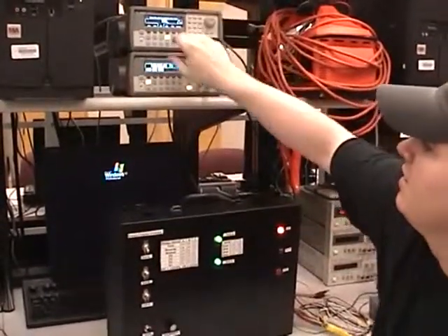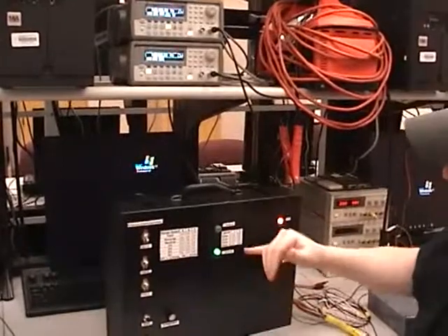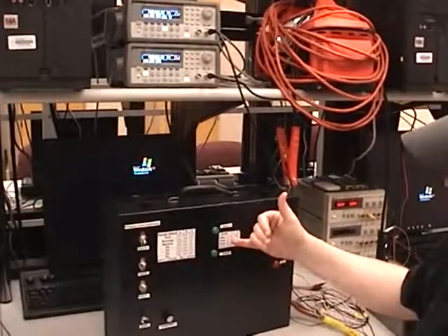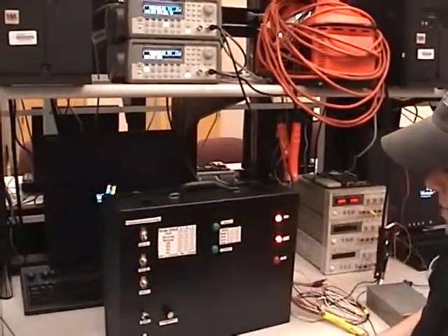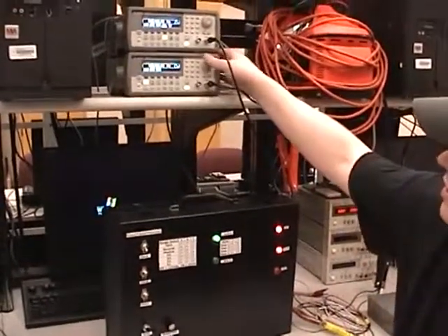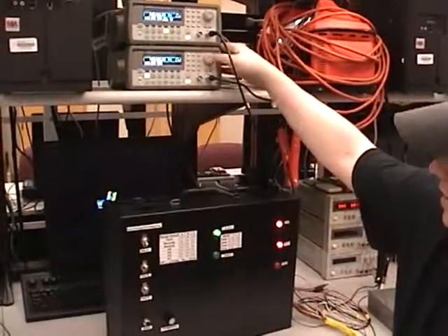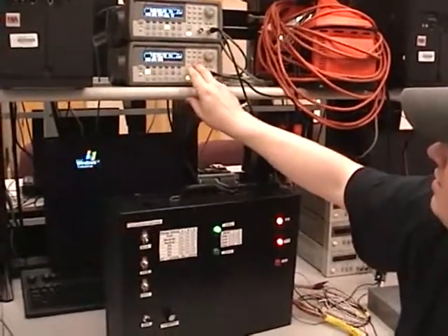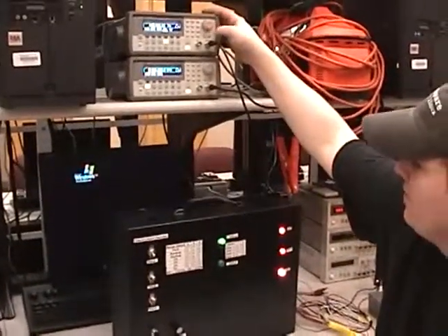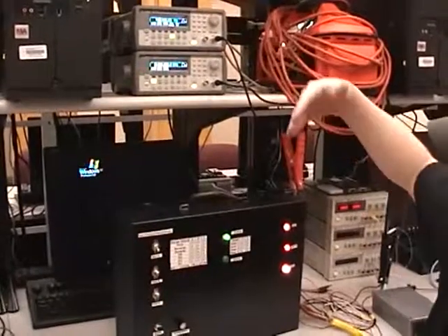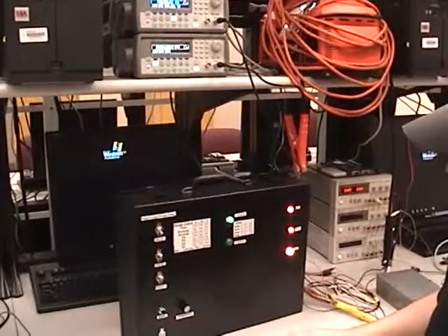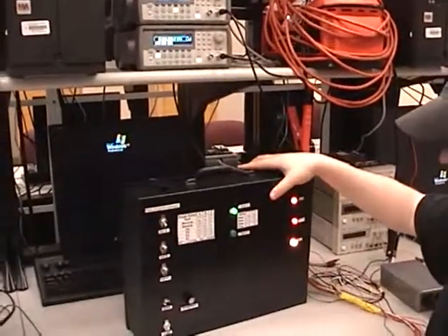So we'll show you again that it shifts, and then your RPMs in your car are dropping because your gear ratio has changed, and then it does the analyzing again, and then you see it wait, and then you get the fourth gear. During this time, your VSS speed would increase to hold it in that gear. So if I had it at 3,000 now, you sped up to that. Then after your RPMs drop because you're in that new gear, your car would be held in that new gear. And that's our transmission control module.